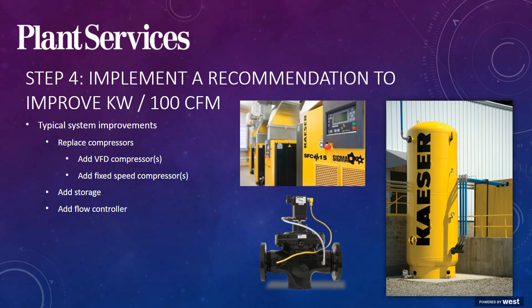Moving to step 4, now that we've analyzed the data, along with what we know from the site survey, we can look at making some improvements. We see a lot of recommendations and requests from end users for variable frequency driven units. In general, top 3 recommendations from cookie cutter audits are new VFD or to replace a compressor, adding a storage receiver, as well as adding a flow controller.